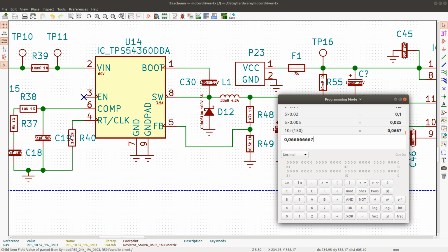That would be the division of voltage times 12. It seems like the input voltage here should be targeted at being 0.8 volts, which is the internal reference as well.